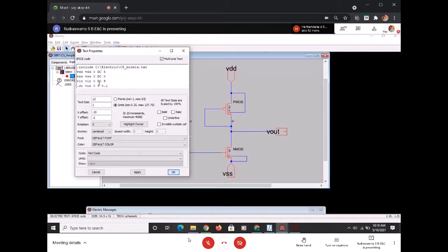So what should be your transient analysis now? V in 0, a sine, parenthesis 0.75. Okay. Input is still, I retain the same thing. See, input you give as minimum as possible. Don't give it in terms of 1 million. You just give small, because we want to see the amplification here, right?